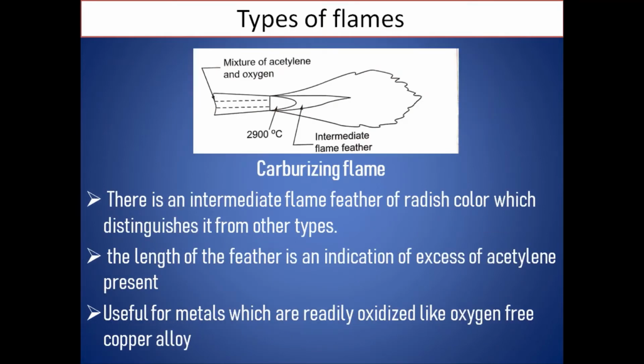Then in the case of carburizing flame, as I told you already, the acetylene amount will be more than oxygen. In this case, oxygen will be less compared to acetylene, and because of this the temperature will be less than the neutral flame as well as the oxidizing flame.